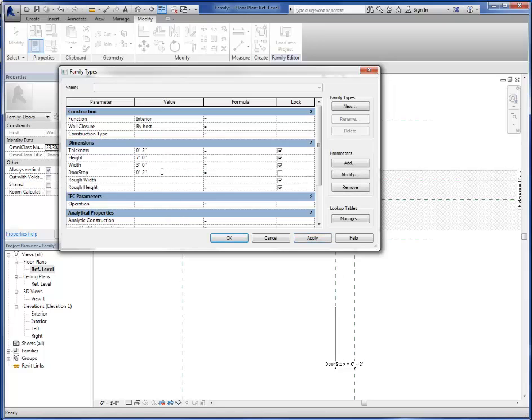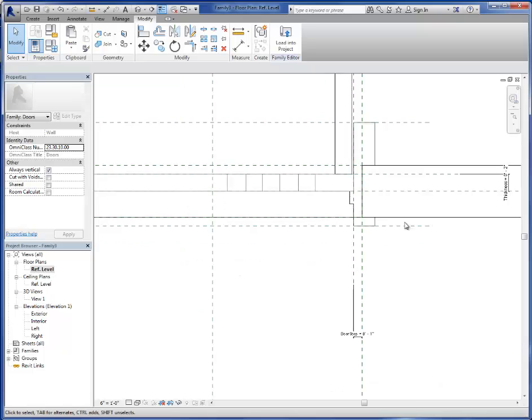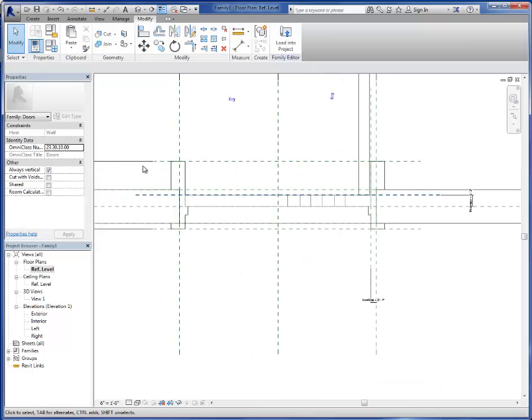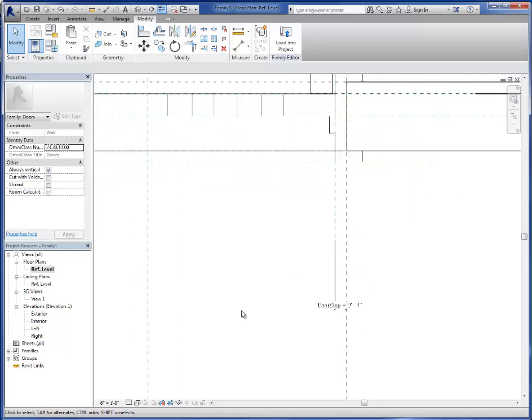That's just because I was turning it into feet here. Essentially throwing that into 2 feet would have had a bunch of overlapping, made a lot of bad geometry, so it was erroring out.